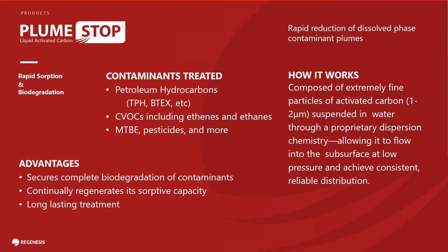This dispersive polymer means that they behave and act as a colloid. So blood is a colloid, wine is a colloid. They move very freely in the subsurface. So distribution is really important here. At fractured bedrock sites, you don't want to be injecting hundreds of wells to get interconnectivity of radius of influence. Though sometimes that is necessary with these Plume Stop jobs where you are dealing with very high contaminant loads. But here we had lower dissolved phase concentrations, so we could get away with wider spacing.